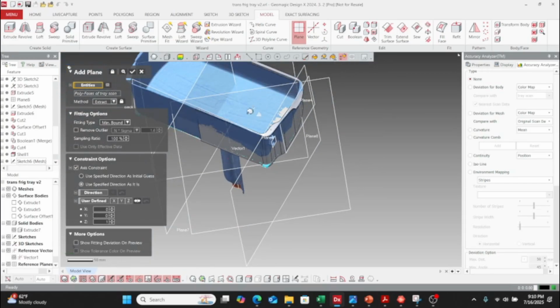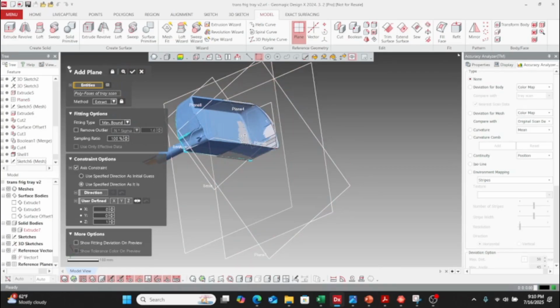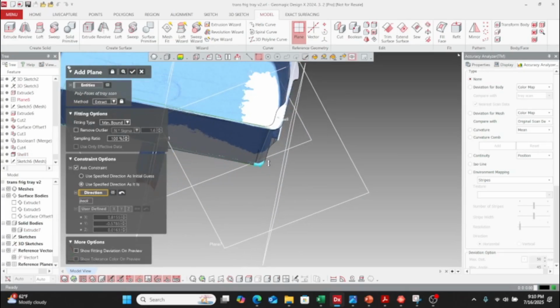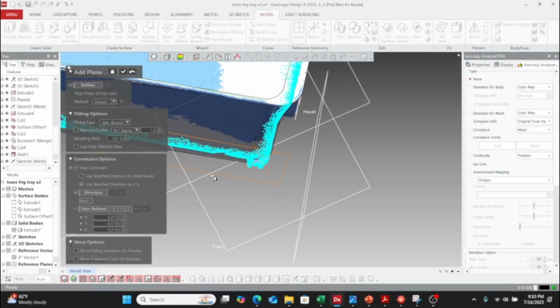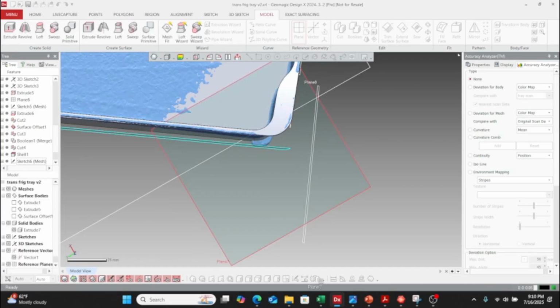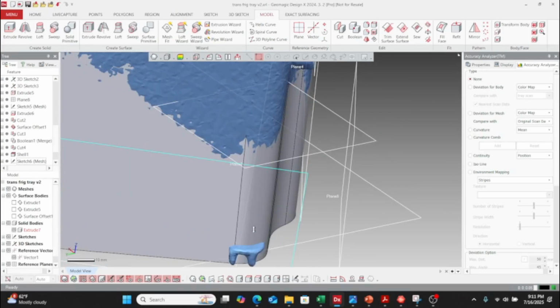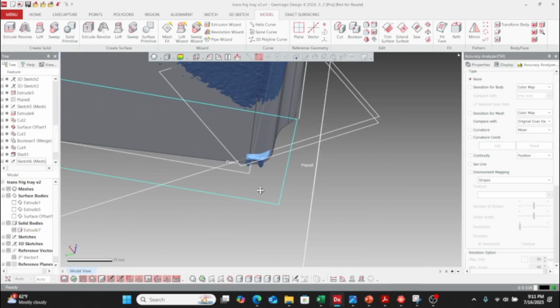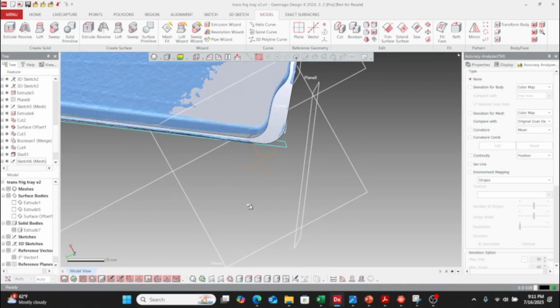And so we need to have them there, or else the tray is going to overstress the joint at the top. And so it's important that we capture this. So we use a parallel plane approach again, where we grab the outside of that data, kind of like we did when we set up that center plane. And we just visualize, make sure we got that. And that looks good. So now we got a plane there where we want this body to extrude to, this little nub feature.